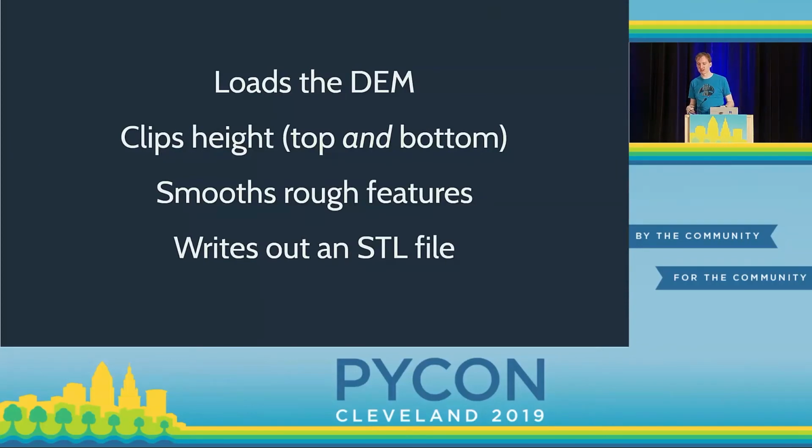First of all, again, we have to load in that digital elevation map, the DEM. And then there's some interesting steps, because I didn't do the middle two steps of this the first time, and the result was spectacular, in that it was totally impossible to print. First of all, you've got to clip your maximum height.